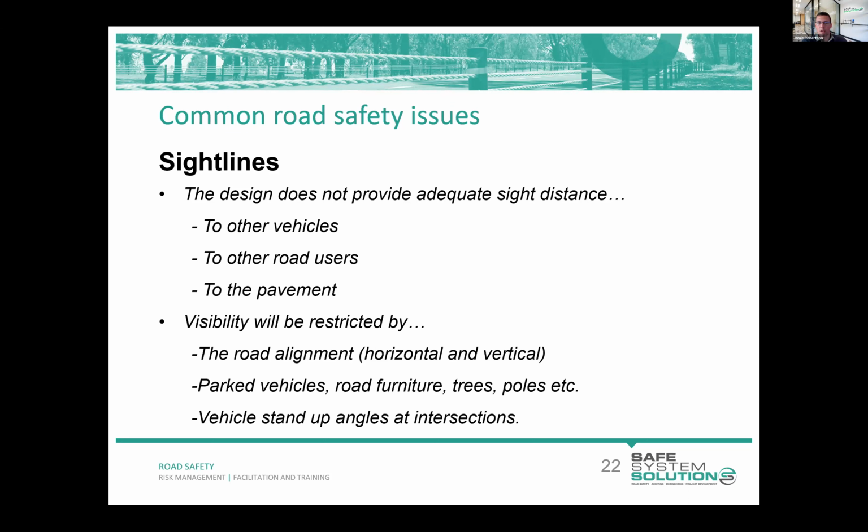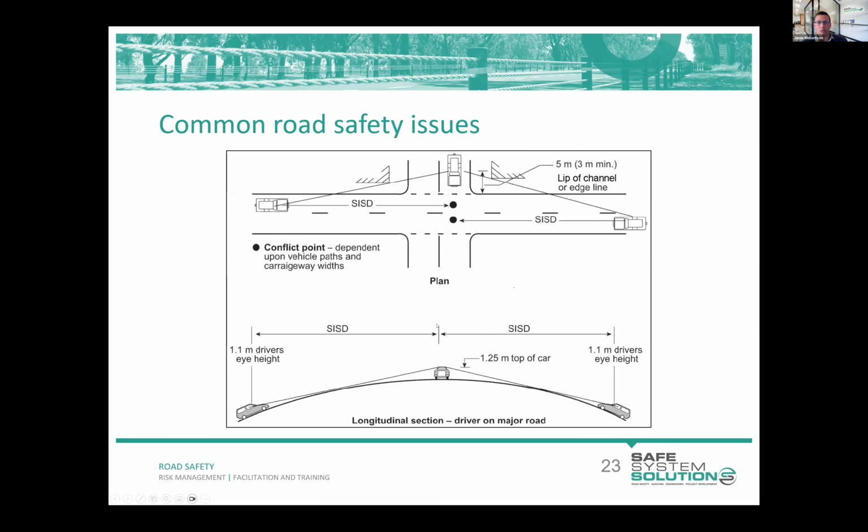It's where you have those acute approach angles or Y intersections that it can be difficult to view traffic approaching from at least one direction, and where we do see higher crash rates. So when it comes to sight distance, there's a whole list of different sight distance requirements that are all covered in the Austroads guides.